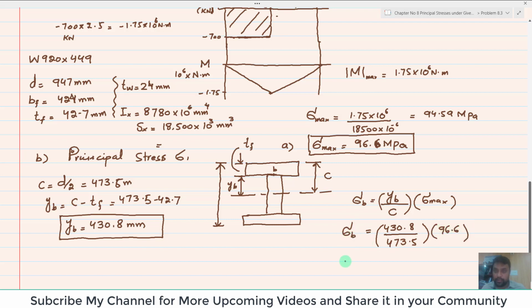So when you calculate it, this sigma B will be equal to 86.04 megapascal. So you can see the stress is reduced because the maximum stress will be at the outer surface of the beam.